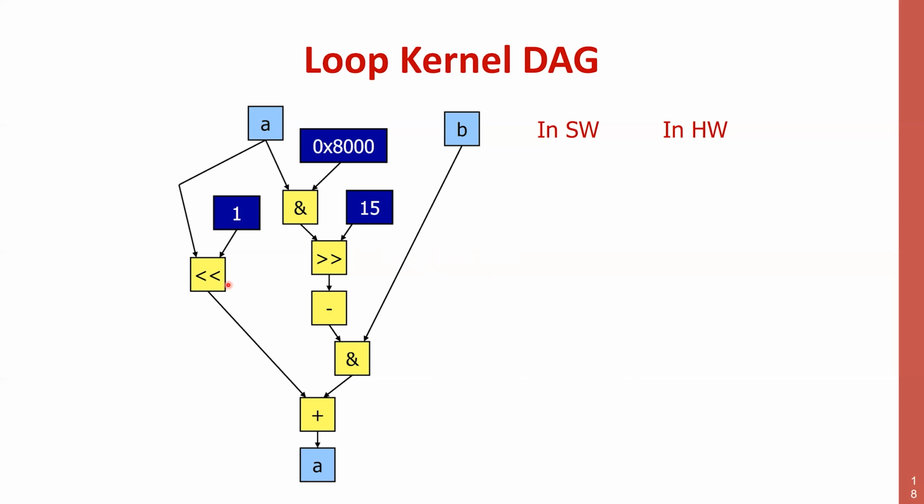So imagine a pipeline a bit like MIPS, the simplest pipeline that you can consider, with all the forwarding paths. If I have forwarding paths, basically I do this in one cycle, I do this in one cycle, and so on and so forth. So essentially I need one execute cycle for each of these operations. So more or less, the length of my loop is about 6 cycles.